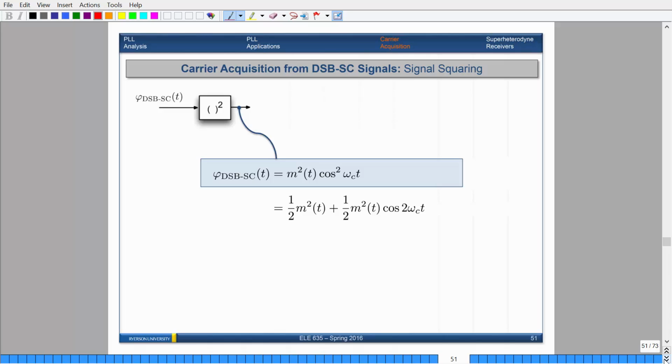Okay. So remember that we have a formula where cosine squared of x is equal to what? A half plus a half cos 2x, okay? And this decomposition breaks down into this and that. That's pretty standard, all right? And then also, because m squared of t factors into this, you will get this as the output, which is standard. We already know about this. Okay, but notice that we have m squared now instead of just m by itself.